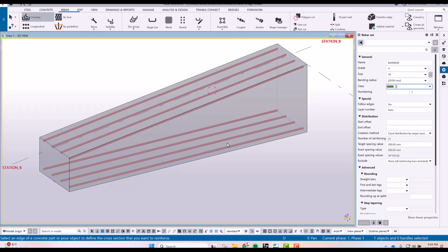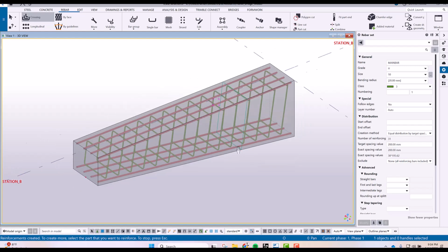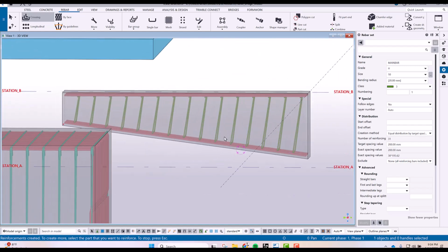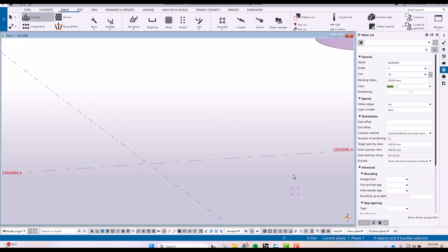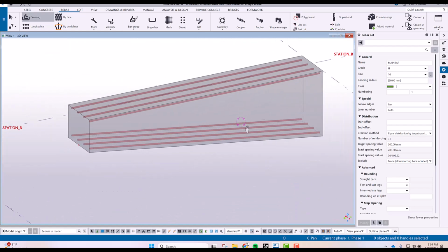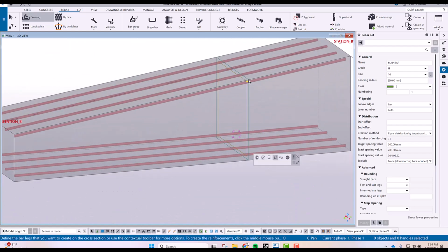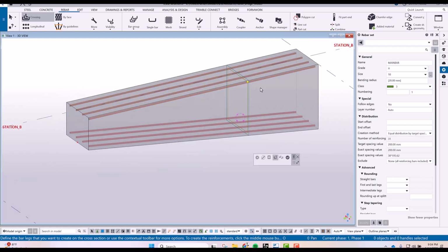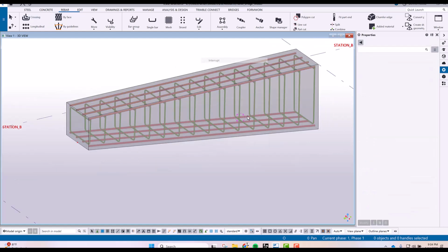If I click the bottom edge, it will be diagonal. It is perpendicular to this edge. If I click this one, let's see. So this is how it looks like, right? But that's not what I want. I want to have a parallel or perpendicular to the top. So click this one and then middle button of your mouse, and there you go.